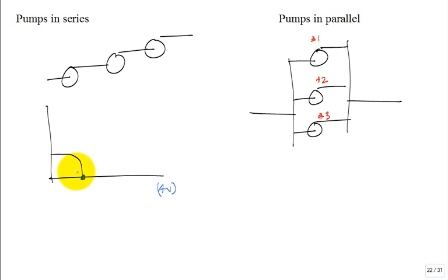So I'm not going to get a higher free delivery through the whole 3 systems. But what I'm going to get is a head gain, and then a head gain, and then a head gain for whatever operating point it's at. So basically you take that one pump, then you add to it another pump, then another pump, and so the composite curve would be way up here, and then it would fall off, come down. Maybe I didn't do the shoulder correct. Maybe the shoulder needs to be tucked in a little bit more, but I think you get the point, that the head is 3 times higher.